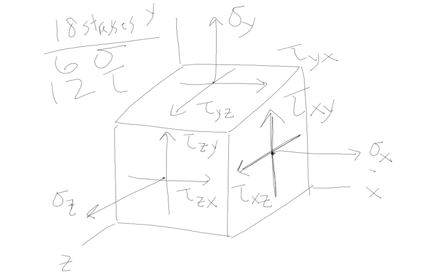This sigma x on the right face must be equal and opposite to the sigma x on the left face. They're opposite in direction, but equal in magnitude and in sign, because they will both be either in tension or in compression. So there's only one sigma x, even though there's a sigma x on 2 faces. They're the same value. Same thing for your sigma y's and your sigma z's. So even though we say that there are a total of 6 sigmas on a cube, there are only 3 actual values.